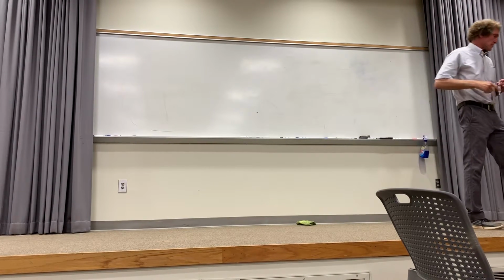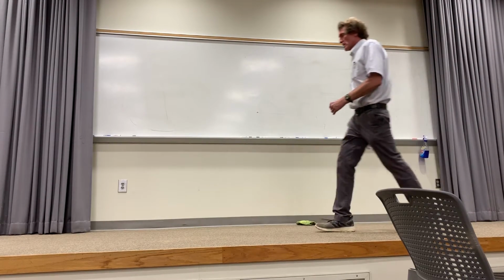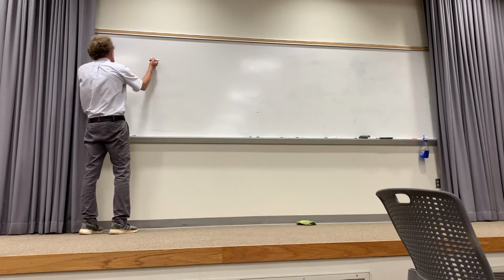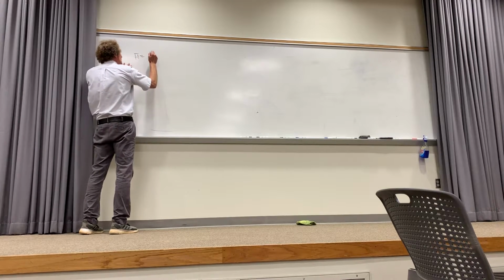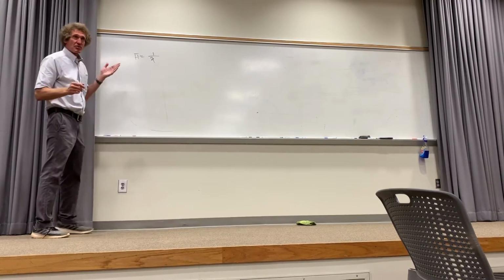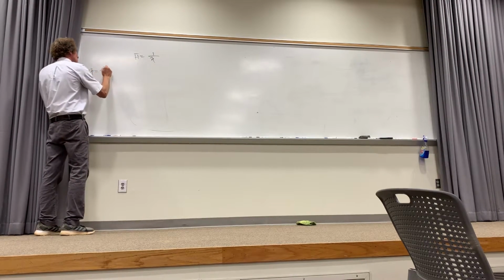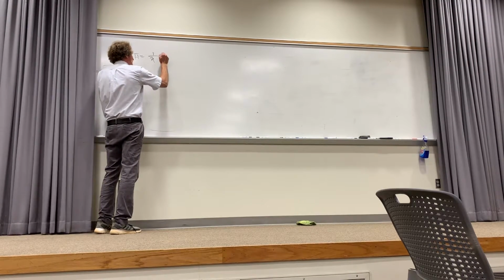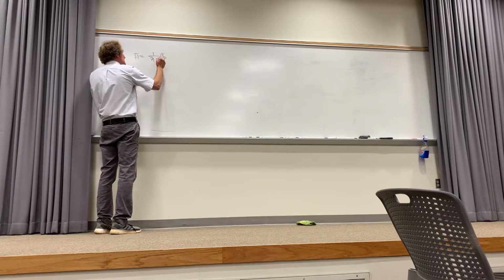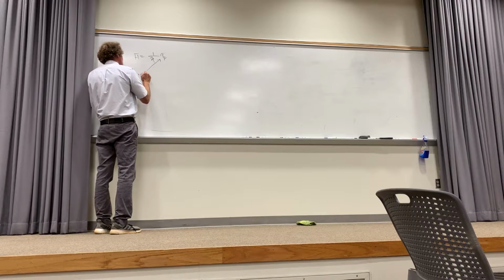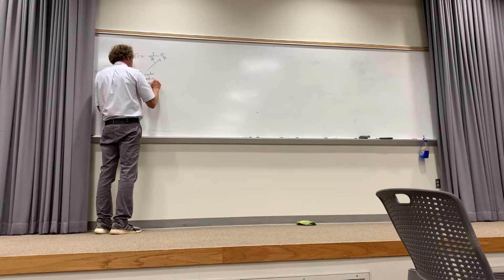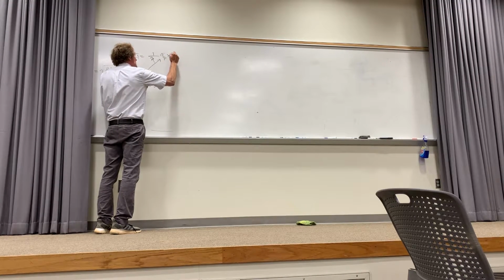All right, the next thing we're going to talk about is how we get H from E simply. Write this down. The H field can be gotten as 1 over the intrinsic impedance, which is what I just showed you before, square root of j omega mu over sigma plus j omega epsilon, times a_P. That's a propagation vector, a unit vector in the direction of propagation, and it's crossed into the electric field.